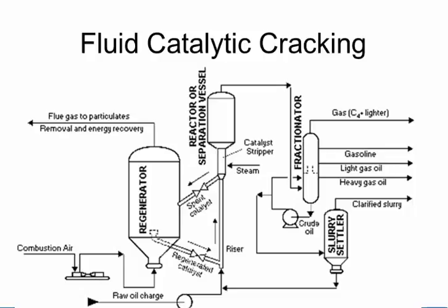Light gas oil to heavy gas oil, that range is your diesel mix, depending on the type of fuel that's going in. Heavy gas oil can be used for some of these gensets, generators. As you go heavier in the gas oil range, you get your real crap stuff, real thick rubbish, which can be called bunker oil. So you use a bit of gas oil and mix it with bunker oil and reduce the viscosity, so you can pump it, and it is generally burnt quite happily in ships.